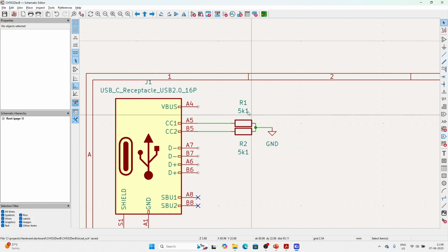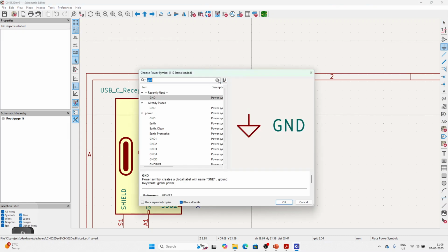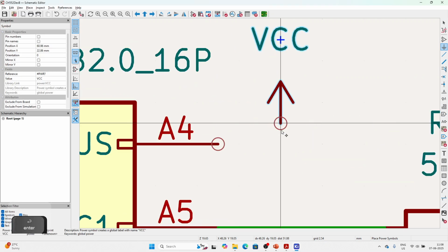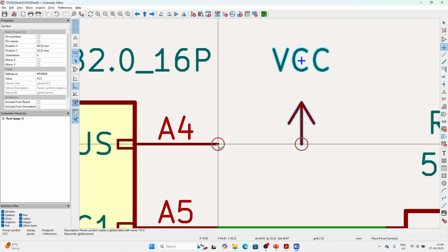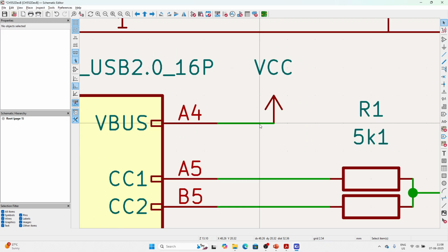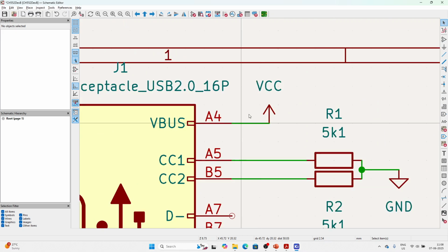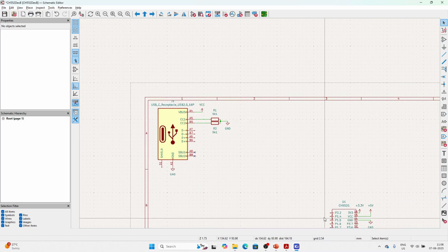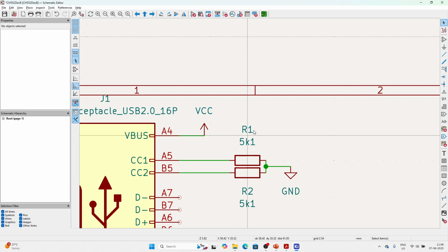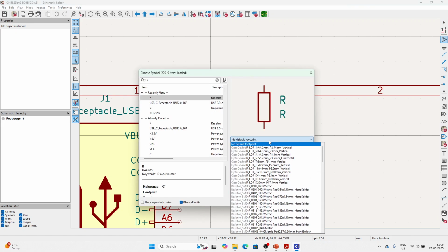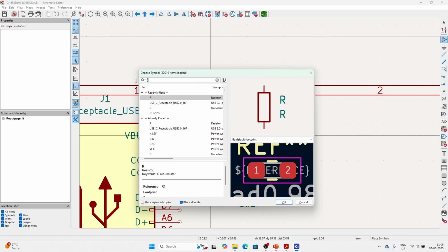but here we are keeping things simple. So let's say VCC here. Usually if we have this at 5.1, this gives 5 volts. Just to make sure that if someone connects directly on the pin here, we have a safe connection, let's use a diode.